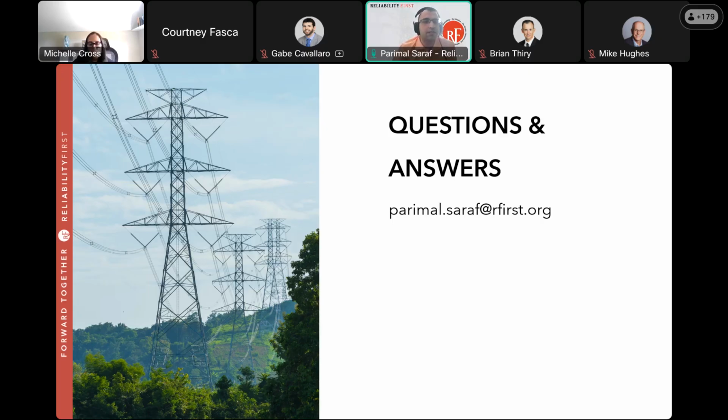So computational challenges are the main restriction right now, and that's why a lot of the studies being done using EMT platforms are very localized studies, where there are a lot of IBR units, or there's a weak grid condition, or there is a risk of subsynchronous resonance.